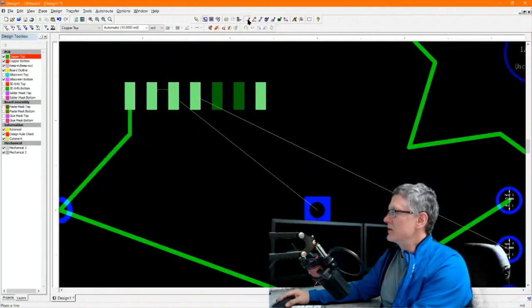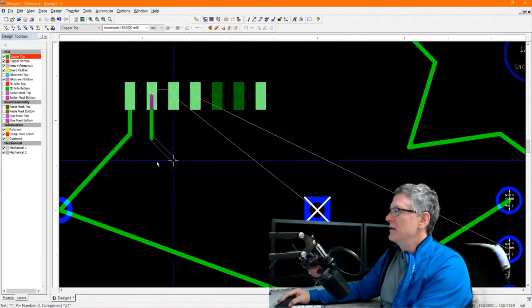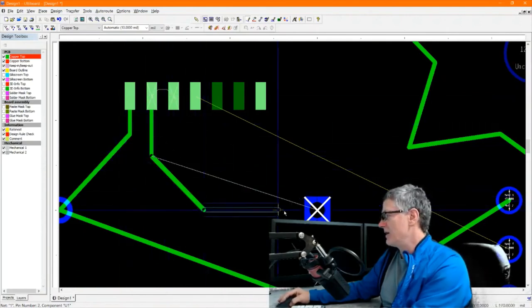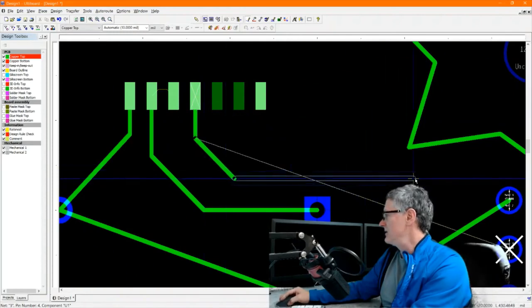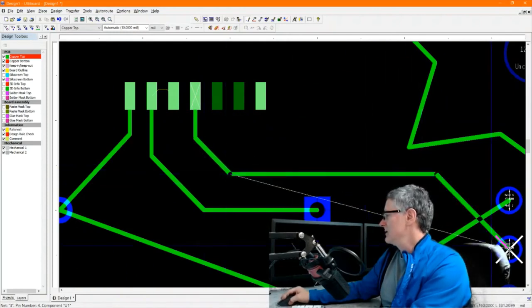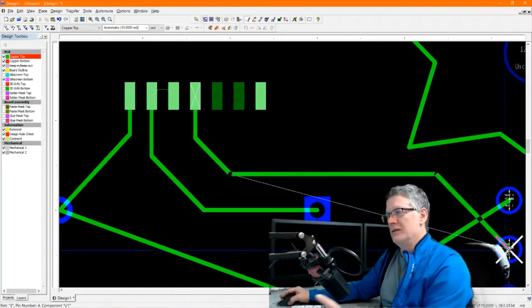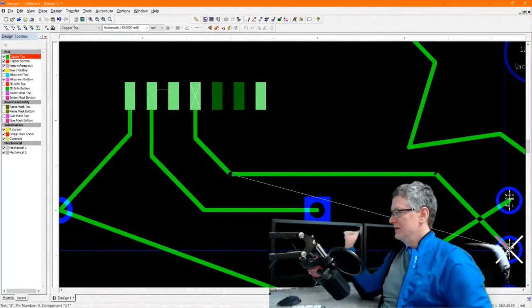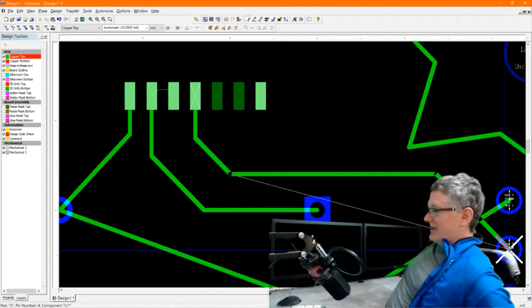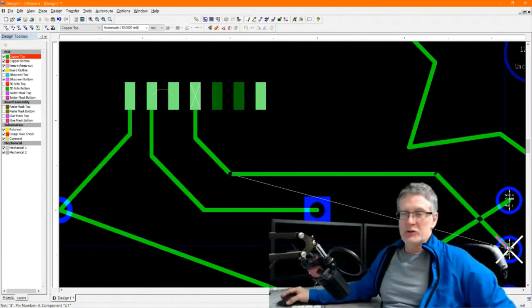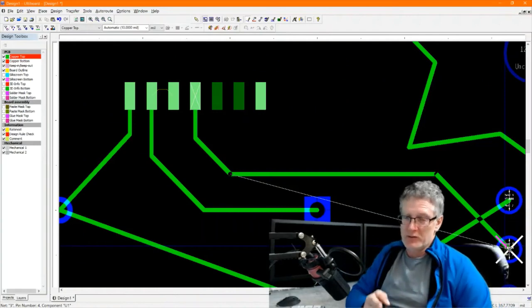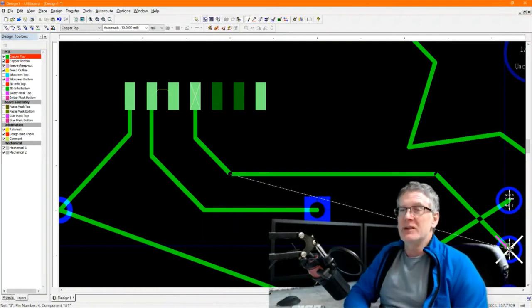And I can route. So I'm going to route over here. So now I'm back on the green layer. There's an easy route. If I route over here, if I put two traces on the green side of the board, the top side of the board, that cross over each other, that is going to be a short.